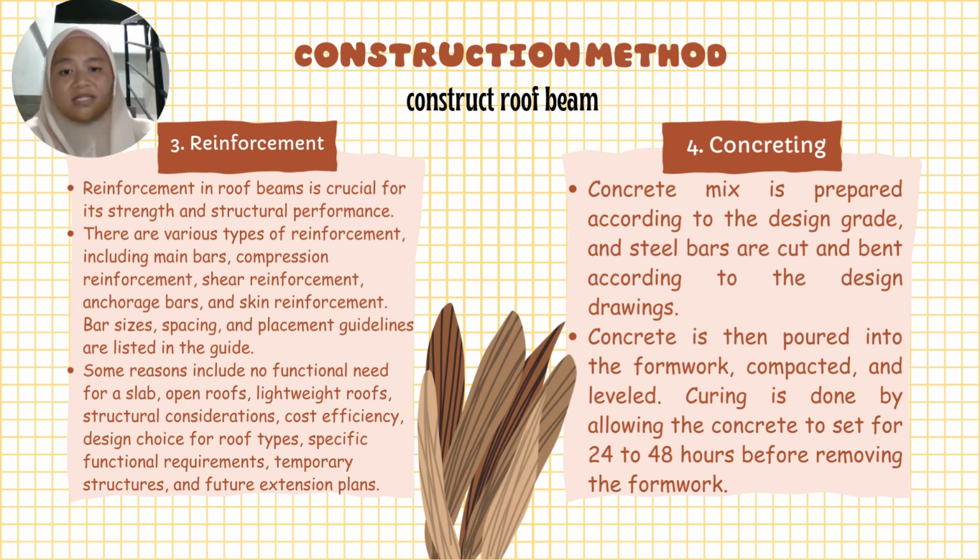Shear reinforcement prevents cracks caused by shear forces, anchorage bars secure the main bars in place, and skin reinforcement is used to control cracking. The size, spacing, and placement of these bars are specified in the design guide. Reinforcement is especially important for structural strength, cost efficiency, and future expansion possibilities.